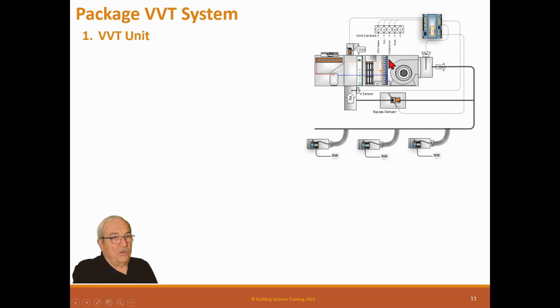We have a DDC overlay. Remember, this is a standard package unit, so it has its control connections up here. This controller now is running this valve. It has this Velocitrol, and it has a temperature sensor because the space temperatures no longer run this package unit. So that's how these work with the systems. Other than that, it's a standard package unit.